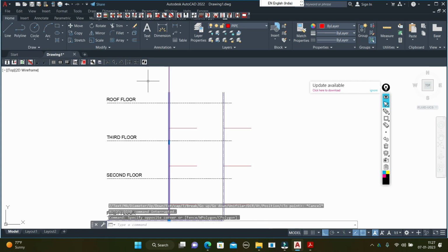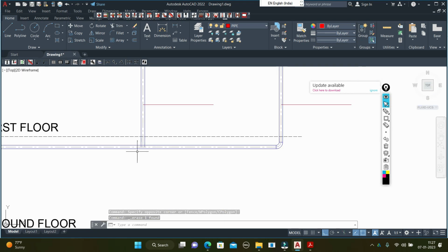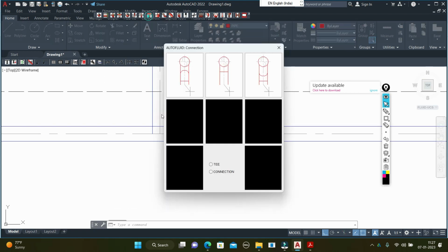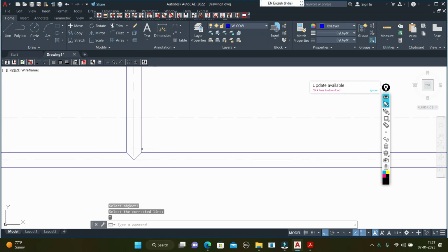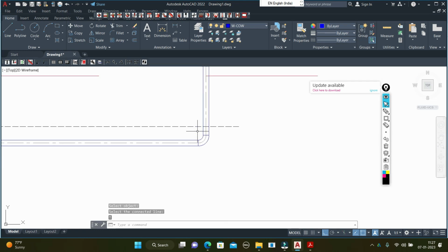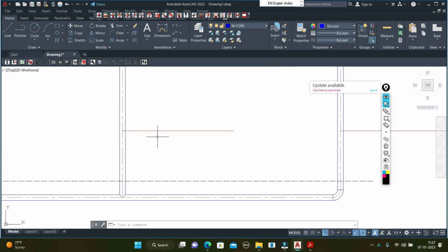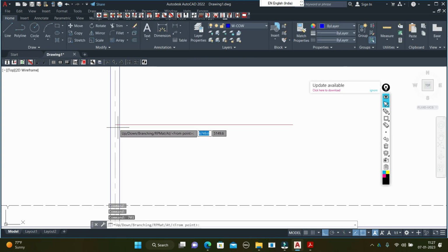Okay, it's serving more than 2 landing valves, so its size should be 4-inch. For the branch, it should be a branch like this one, this one and this one. Let's make a perfect branch. This one also. And for each landing valve, the pipe should be 65 mm diameter.